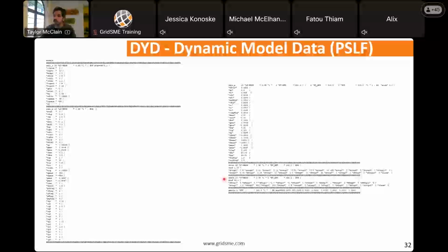And so you assign this model to a generator at a certain bus. Now when you pair this dynamic model with your steady state model that you've prepared, you can see how your generator would respond to system disturbances such as faults. The most common that you're going to see is the POI fault done for new generator interconnection requests. That is testing the dynamic response of the facility to a fault at the POI.